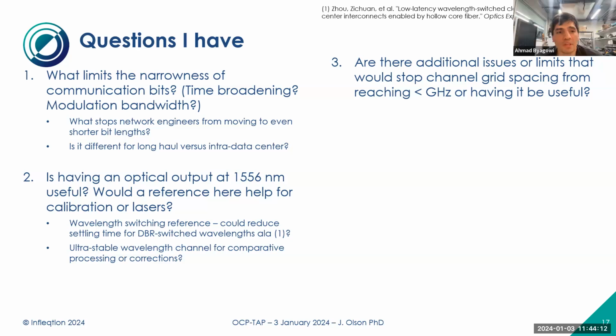One thing, thinking practically about these things: when you look at channel capacity, we rely heavily on the eye chart. We want to keep the eye open, and I might be wrong, but when I have such an approach where I'm looking for the eye to stay open, this is basically an asynchronous method, where I'm trying to recover the clock from the adjustment of the signal that I am getting. Because again, there is no separate line to provide me the clock to have a synchronous thing.